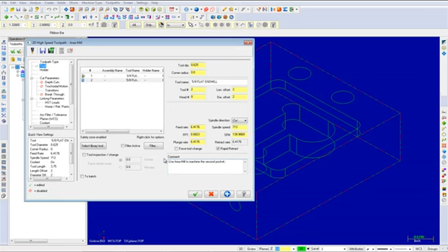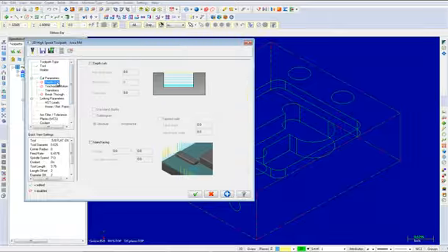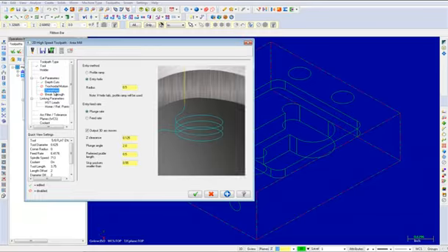Since the toolpath has been copied, all the parameters remain the same. Therefore, the only parameters shown are the ones we will be changing. That being said, select the depth cuts. Enable this option and input a max rough step value of 0.25. Next, select the transitions. Enable Profile Ramp and enter a preferred profile length of 0.75.